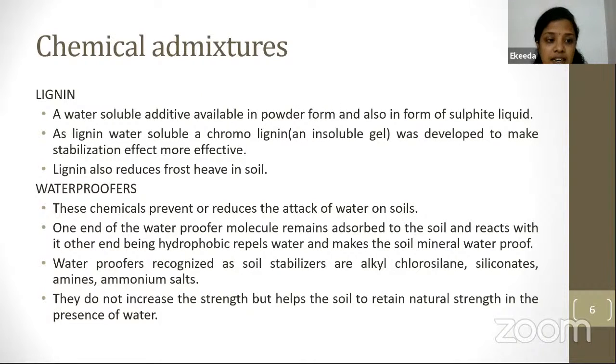Now next is lignin and waterproofers. Lignin is an admixture that we are adding to the soil. Lignin is a water soluble additive available in powder form and also in the form of sulfide liquid. As lignin is water soluble, a chrome lignin was developed to make the stabilization effect more effective. Lignin also reduces frost heave in soil.